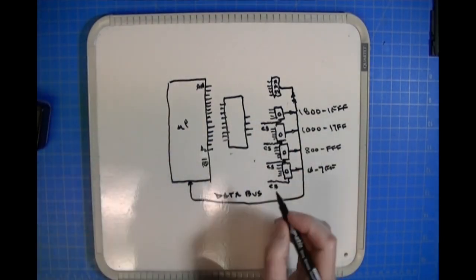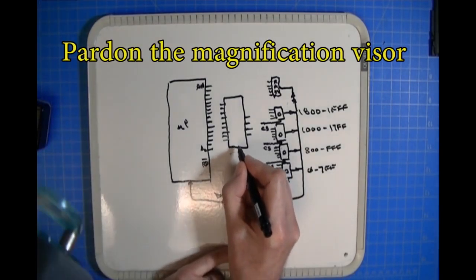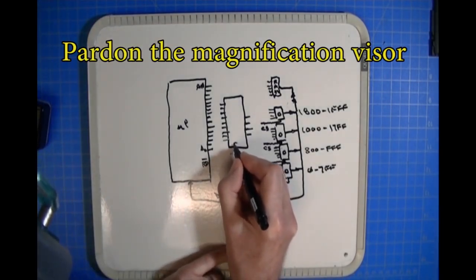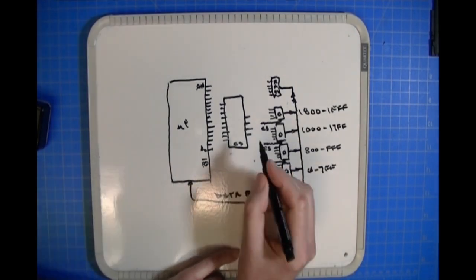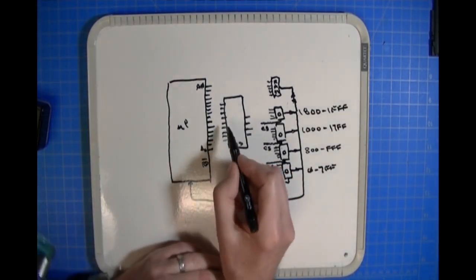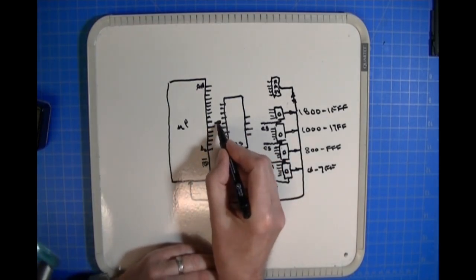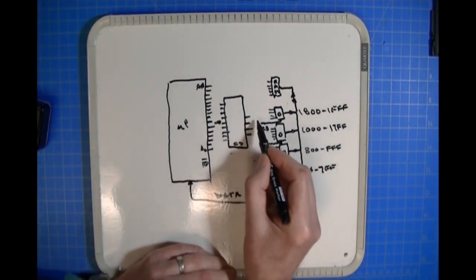You had something called chip select or output, and it would depend on who made the part, but I'm going to call it chip select. Okay, so you've got address lines going into the bipolar PROM here. These guys are going into the bipolar PROM. And then you got output lines that are coming out of the bipolar PROM.